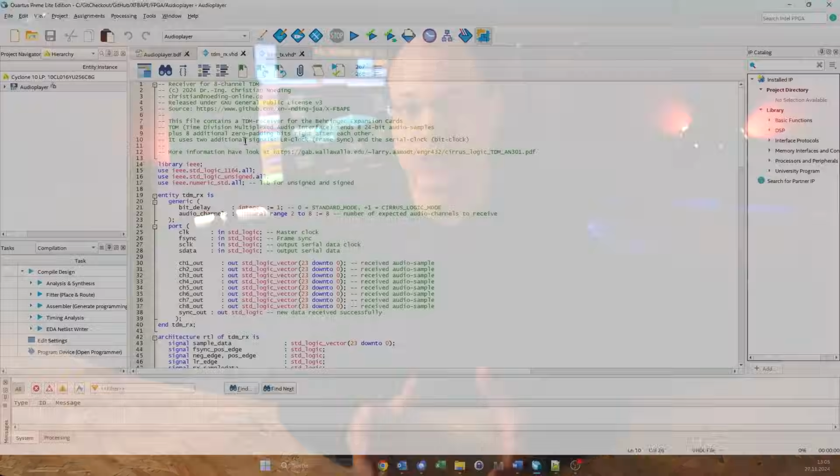Great. The audio mixer from my guitar project already has all the necessary functions on the board. Reading multi-channel TDM, a multi-channel audio mixer and some EQs. Only sending of TDM is not yet available, but based on the TDM receiver block, we can set up a TDM transmitter for 8 channels with minimal changes.